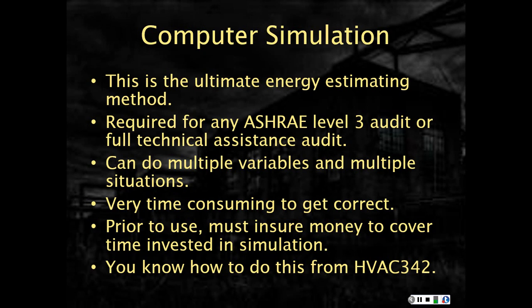Finally, the final energy estimating method is the good old computer simulation. This is required for any ASHRAE Level 3 audit or full technical assist audit. The value of this is it can do multiple variables in multiple situations. It is very time consuming to get correct.